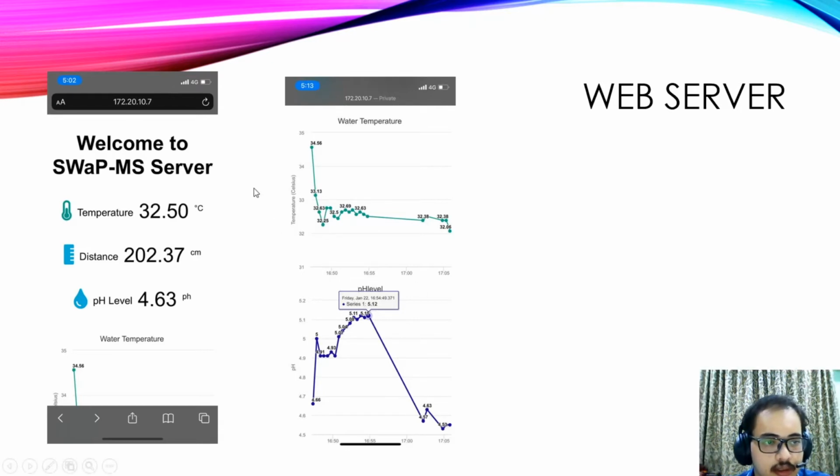To access this server, we must know how to get the IP address from the ESP8266. The ESP8266 acts as an AP, access point, and we need to find the hotspot, which is connected to the ESP8266 as an STA.